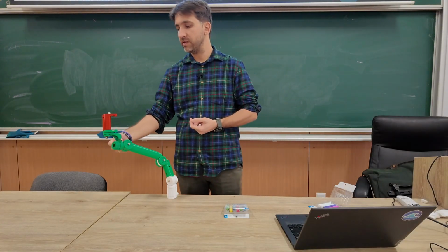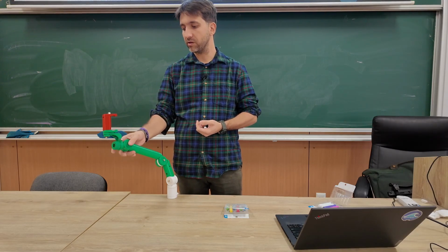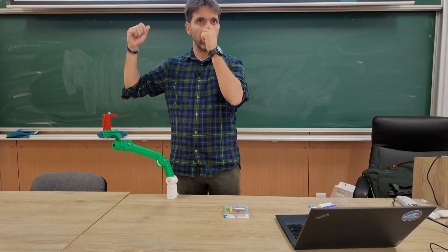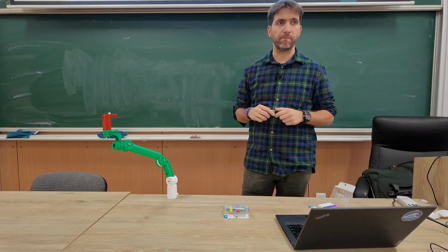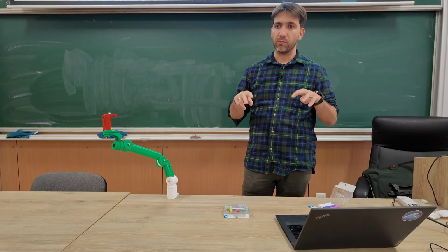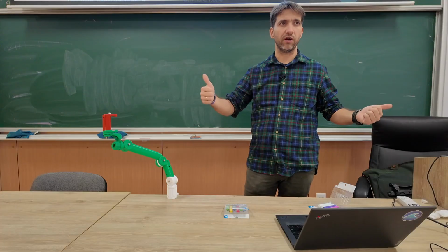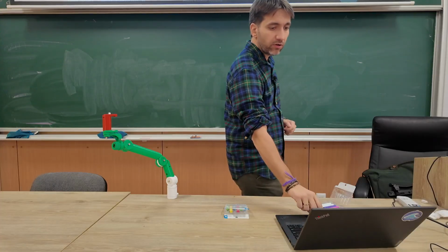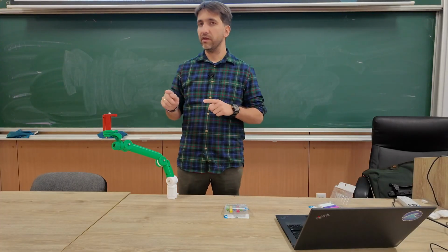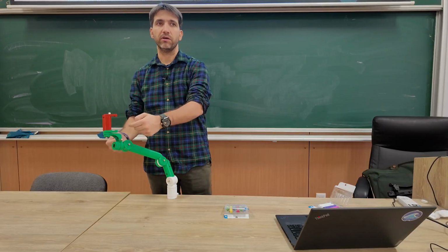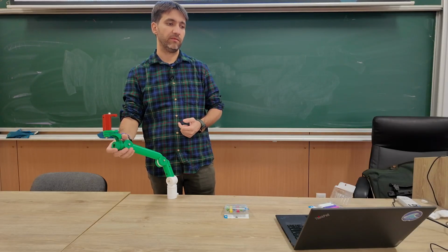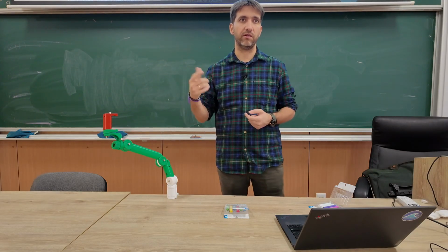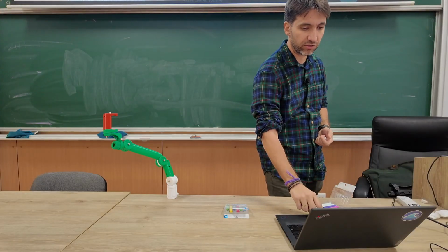So if here I have DC motors, which are typically used in robotics, what would I need to modulate in order to have torque control? What property is actually proportional to the torque, voltage or current? The current, right? So here I say I need torque, but in the end that's very linearly correlated to the current I send to the joints. So in the end, we can say I control the current I send to the joints, and then I have a scaling factor that calculates the torque that I actually send to the joints.